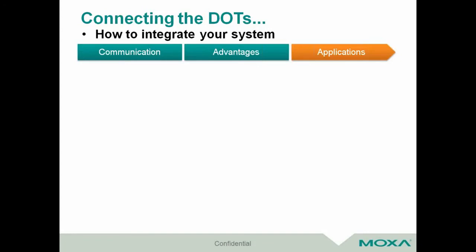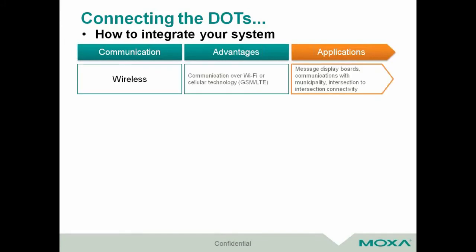Wireless. There are several applications that we use wireless. I know there are lots of applications that use DSRC, Wi-Fi technology, ABGN, and in some cases, cellular technology. In some applications that you see with the Department of Transportation, some message boards actually just use Wi-Fi or even cellular to push all those serial and ASCII strings together. So getting a reputable Wi-Fi or cellular module device will actually just work for those applications. It's usually used for those remote applications that you want to deploy, probably pushing data back, whether it's streaming video, and it's possible. You just have to understand the requirements of that.